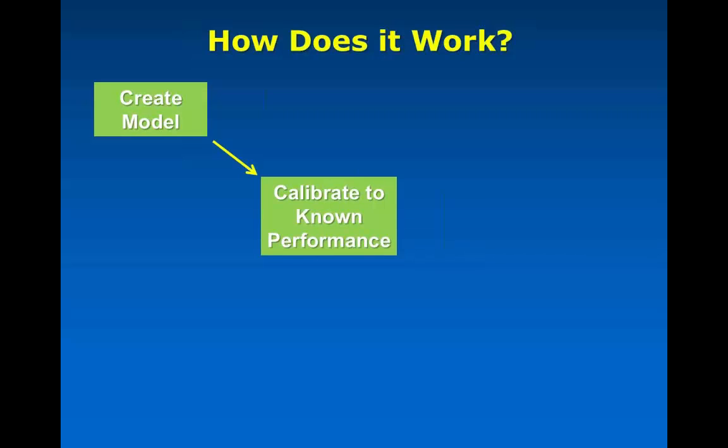Setting up the model and creating it in GPSX is fairly straightforward. Taking the time to go through your data and find a good time period to use for your calibration, getting that data into GPSX, and iteratively going through the process of making parameter changes to calibrate that model, that's usually where the major effort is, and where a lot of the knowledge and experience that comes with doing modeling comes out.